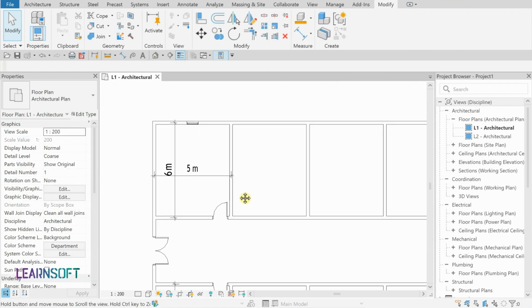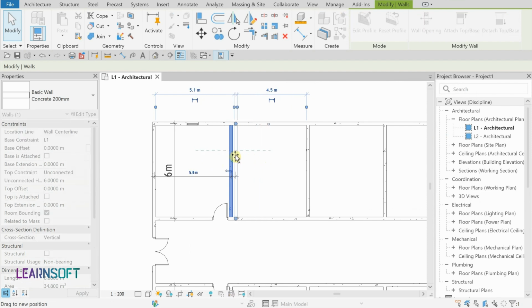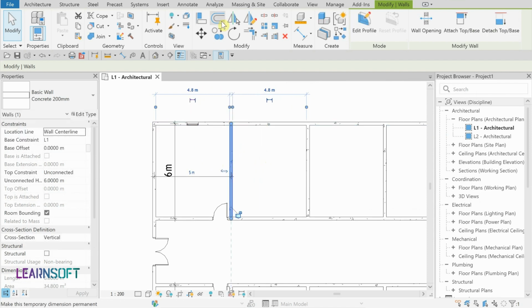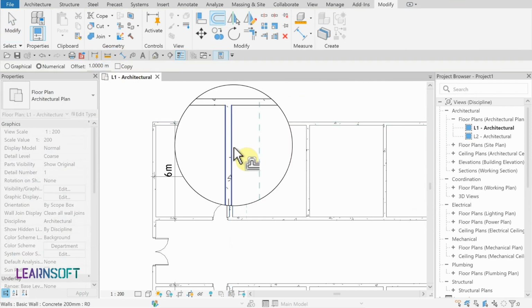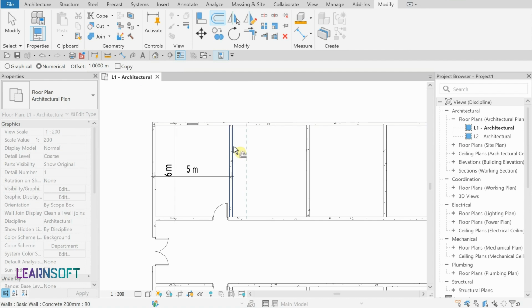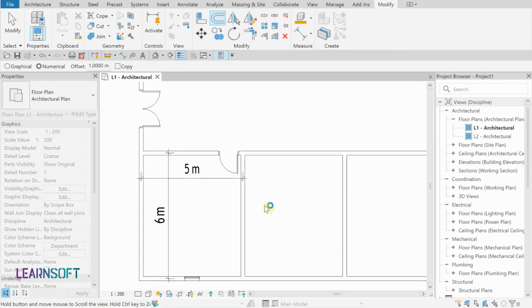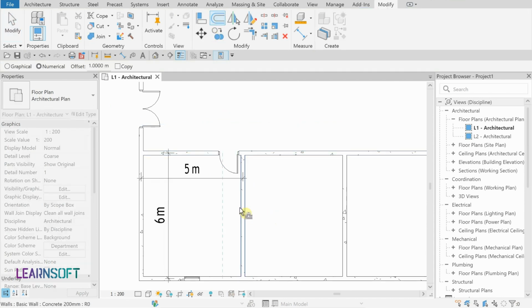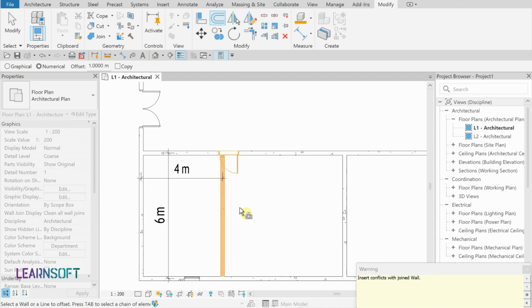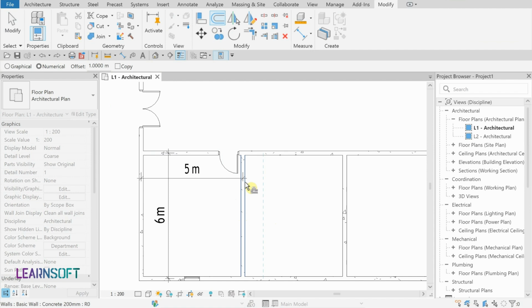For example, we want to move this wall to the left or right. How can Offset help us? Select Offset or type OF, then deactivate Copy. Then click on the side where the wall is going to move. I repeat again, please pay attention to mouse clicking and movement of the element. With any wrong offsetting or conflict with current elements, you may receive an error message. Click on the correct side to offset.